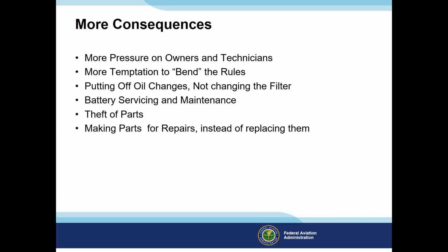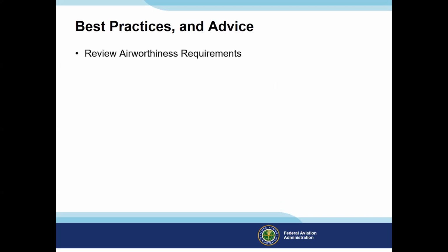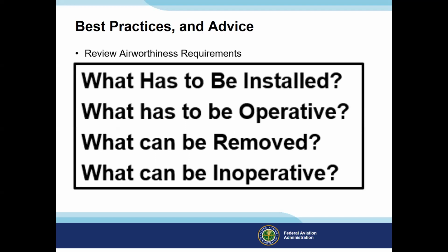So let's review best practices and some advice. Well, review the airworthiness requirements like we've done here tonight. What has to be installed, what has to be operative, what can be removed, and what can be inoperative. And we looked at all those things tonight, so I hope you have a better understanding of those items.